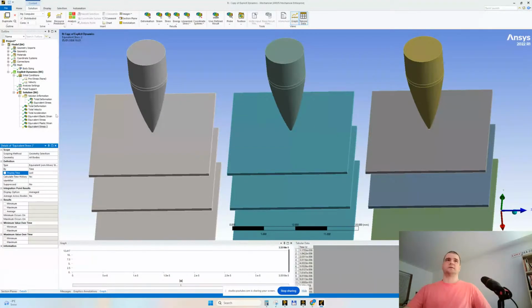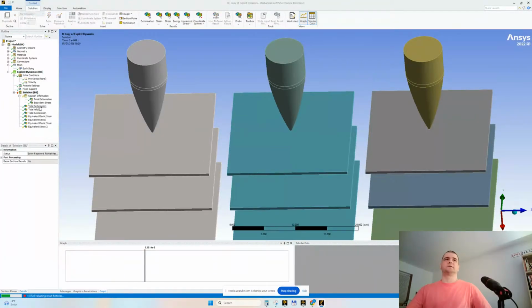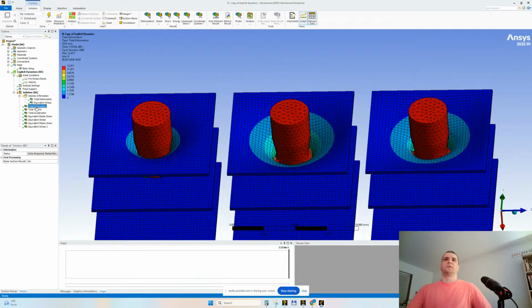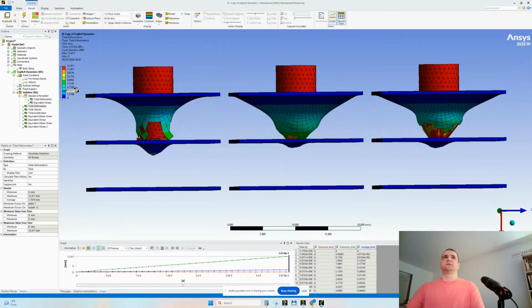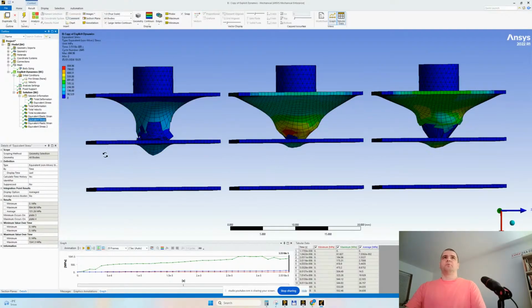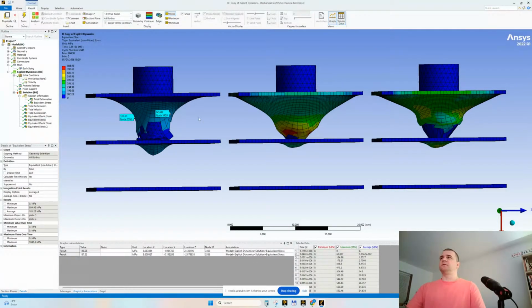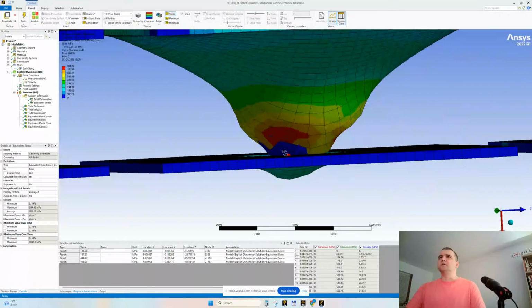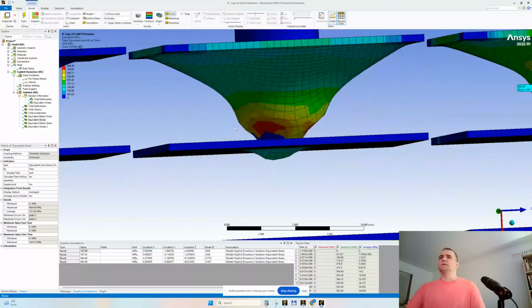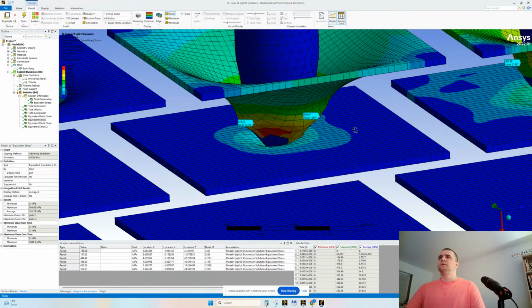Here, let's make this 0 again. Evaluate the results. We're beginning to approach something decent. Equivalent stress. Let's probe a little. Again 140 and again 400, 500. And here, ladies and gentlemen, I think we begin to have fracture here with the bilinear isotropic hardening.